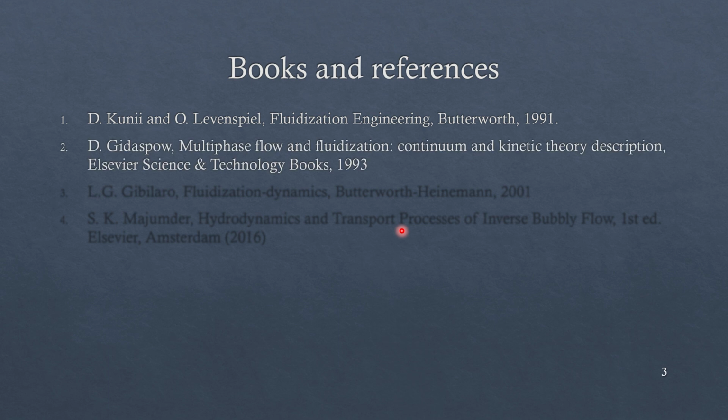And the second one is Gidaspow's Multiphase Flow and Fluidization: Continuum and Kinetic Theory Description. When we are modeling fluidized beds, we can model the solid phase as a continuum or as a Lagrangian phase. In the Lagrangian phase, we track each individual particle, write their equations and solve them.